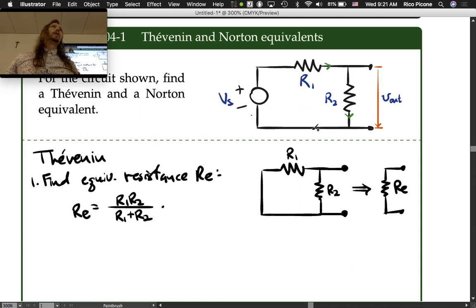So both of the terminals are shared now for the resistors. This one isn't quite as obviously so, but if you follow the wire around, it's connected to the other end of the resistor. So this is another parallel situation. So they started out in series and they ended up in parallel. Sort of something to be watching out for. It's important to recognize how, when you set the sources to 0, that changes the circuit.